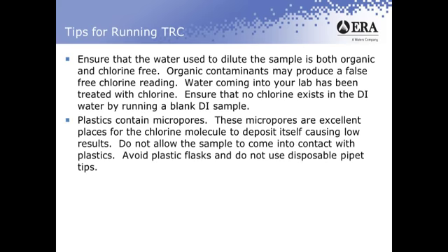The next thing we want to be careful about is to not use plastics. Plastics contain what we call micropores on the inside of that. If you were ever to put anything plastic underneath a microscope, you'd see small pores on the insides of those plastics. And those micropores are excellent places for the chlorine molecule to deposit itself. So if it's sticking to the inside of your plastic somewhere, it's not getting into the sample that you're running, and it will cause low results. So do not allow the sample to come into contact with any plastics. Avoid using plastic flasks. Always use glass flasks when you're diluting up your sample.